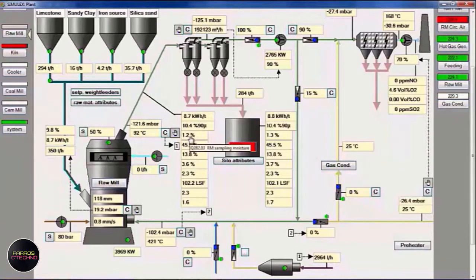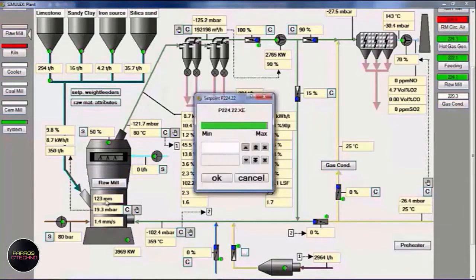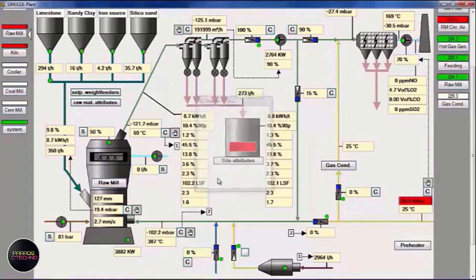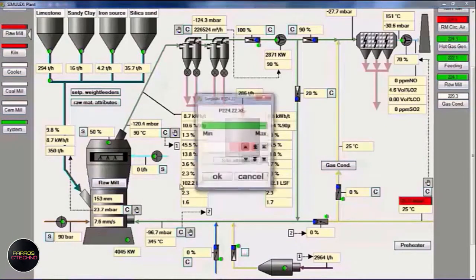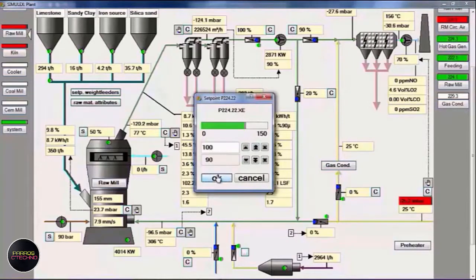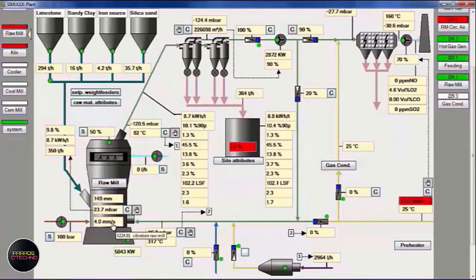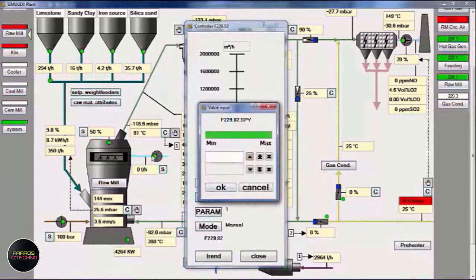The feeding is 400 tons per hour with a moisture content still at 1.2%, hopefully it's below 1 or 0.5%. Here, the bed material goes up, we have to immediately increase it 10 bars, we can see the bed material is still going up, with 350 tons per hour feeding, the vibration goes up, we have to increase the pressure immediately. Let's observe the vibration. If it drops, then the bed material is close to normal operation.